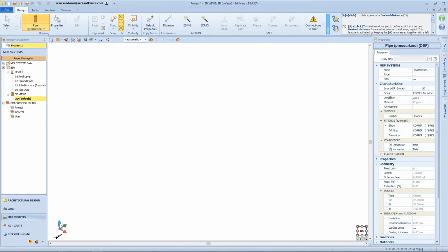The material type is shown in the piping field, which by default for this element is copper. By clicking on the piping field, 3 buttons appear. The plus button allows you to configure a new custom dimension with respect to the geometrical parameters automatically associated with the selected pipe, which will be added to the profile sheet chosen, in this case copper.